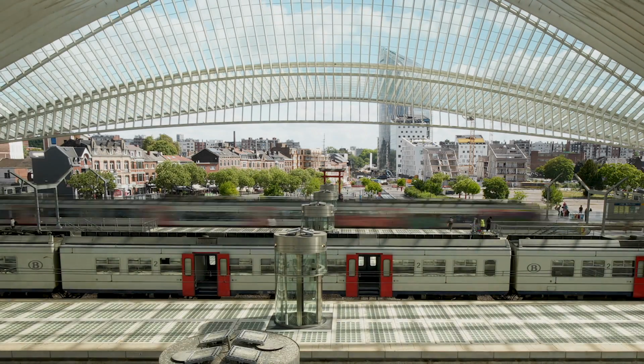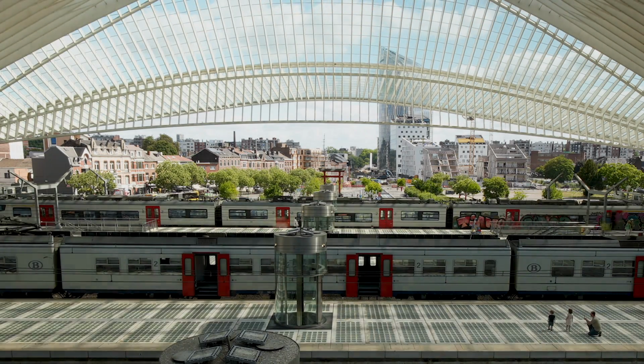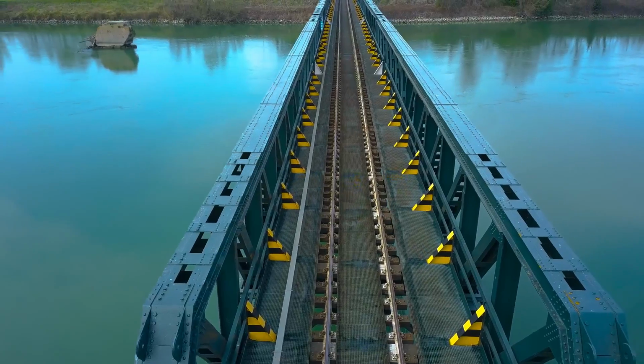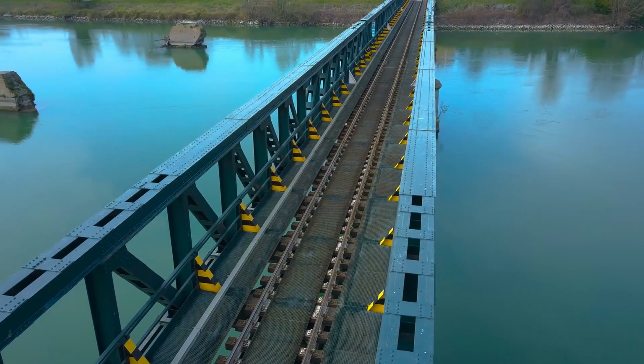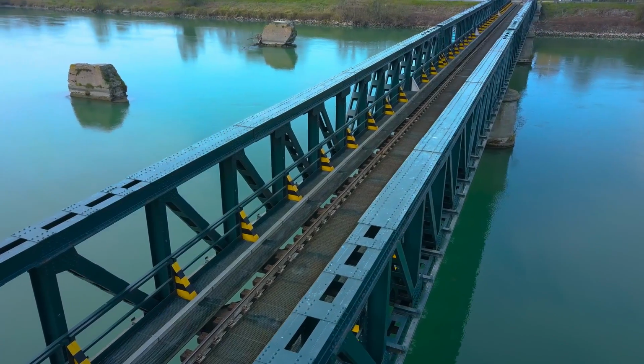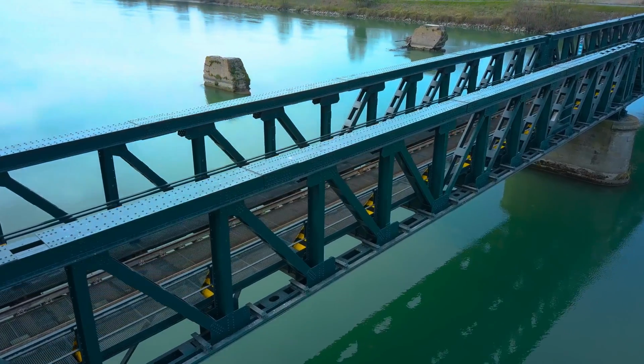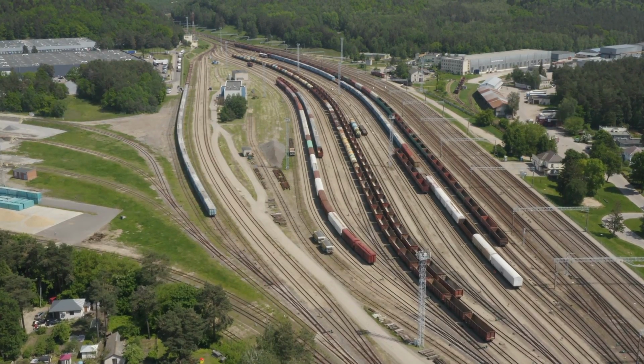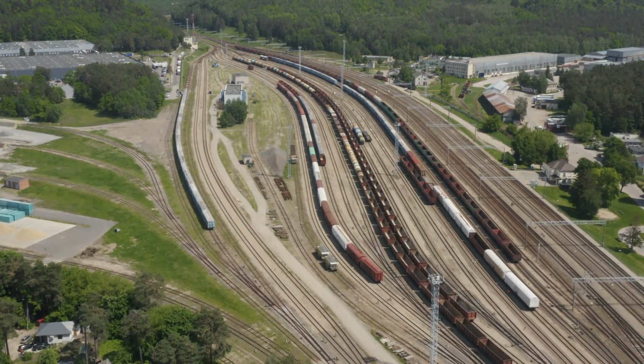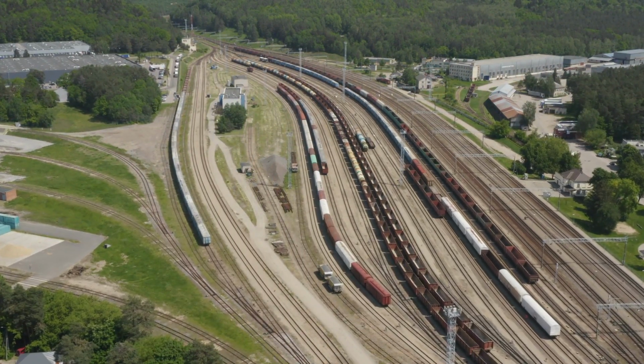Corrosion, deformation and fatigue build up over time. Poorly maintained steel decks can deform, crack or lose integrity at the joints and connections, and in severe cases can lead to ballast dropping through and then loss of track support. Add to that rail creep due to thermal cycling, as well as tamping restrictions to avoid damaging the bridge deck below.